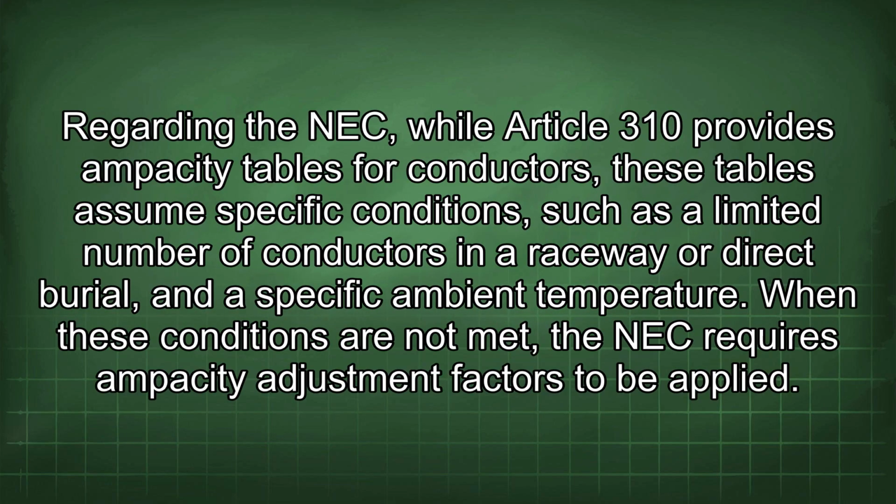Regarding the NEC, while Article 310 provides ampacity tables for conductors, these tables assume specific conditions, such as a limited number of conductors in a raceway or direct burial, and a specific ambient temperature. When these conditions are not met, the NEC requires ampacity adjustment factors to be applied.